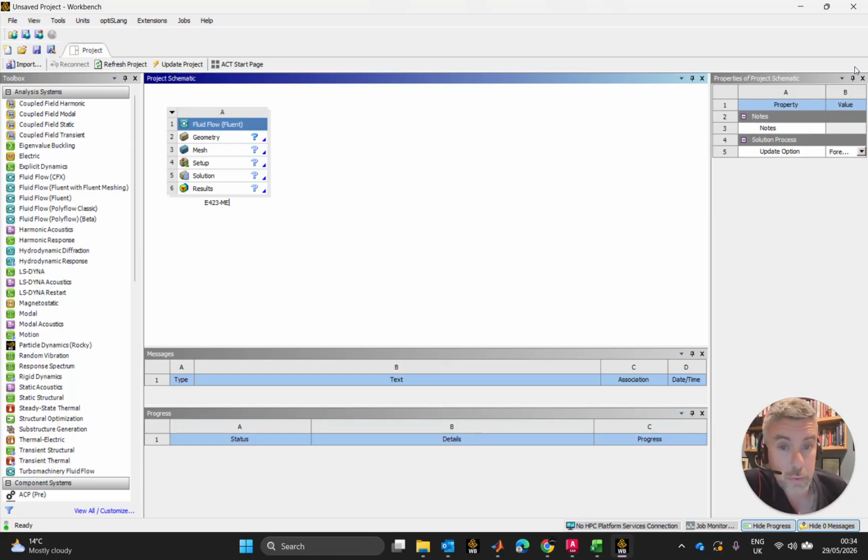Now, here it's only a 2D analysis. We're never going to be able to fully appreciate the lift or the negative lift or the downforce, whatever you want to call it, off the front wing using a 2D analysis. And we're certainly not going to be able to accurately predict the drag, because a 2D analysis, especially if we do it with a steady state solver, isn't going to take on sources of drag and sources of energy, whether we're energizing or losing energy from the likes of vortices and that.